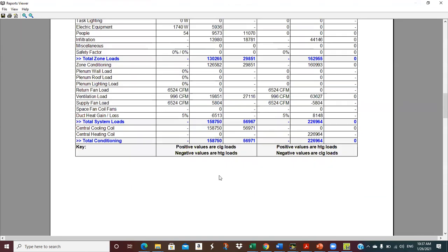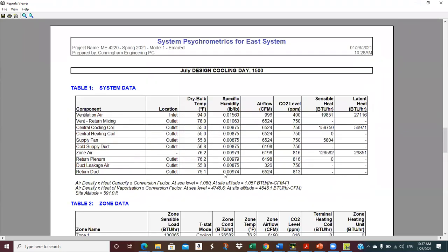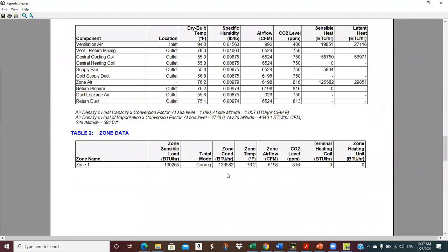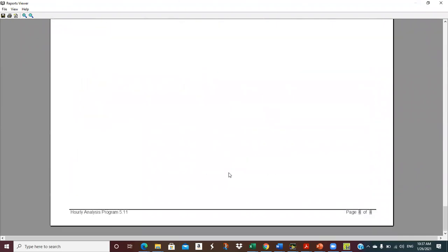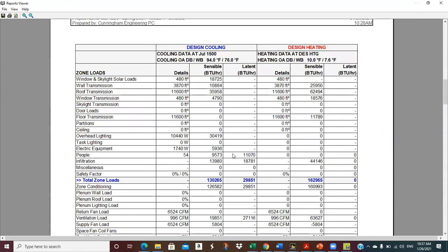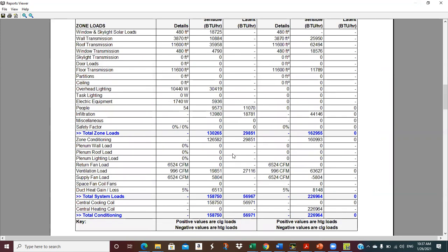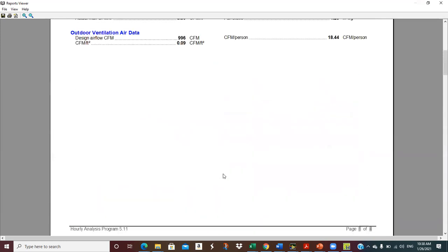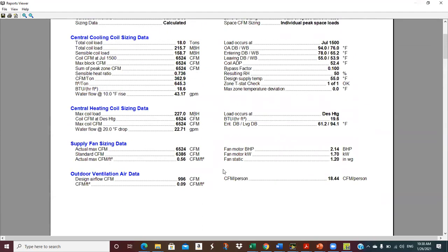Okay, and I don't know, what is this? Oh, this is psychrometric stuff. But anyway, those first two, to me, were the two that I used when I was really doing design. I would pore over this. Because you have to make sure each one of these categories is right, and you have included everything of importance in the building, then you've got a pretty good load. And this kind of summarizes what happened on the detailed sheet.